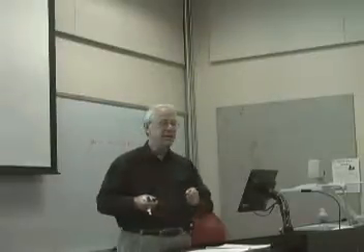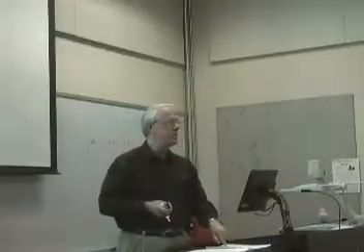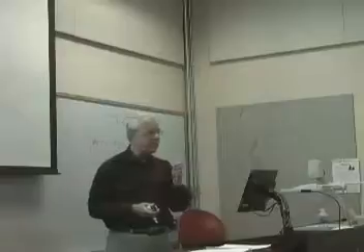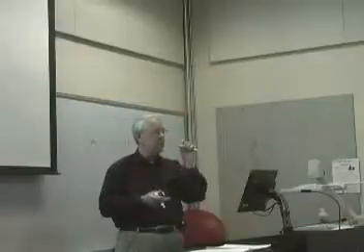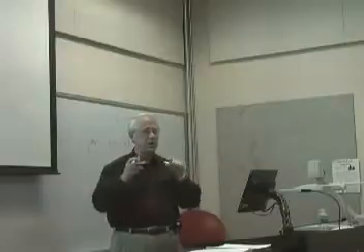A bunch. If I'm going from a 3 by 3 linear element to a 6 by 6 quadratic, how many 3 by 3s in a 6 by 6? A bunch, right? So it's a lot more computational work. So you have to evaluate this. Do I want to use a lot of little linear elements, or do I want to use bigger, higher order elements? That's the big question.